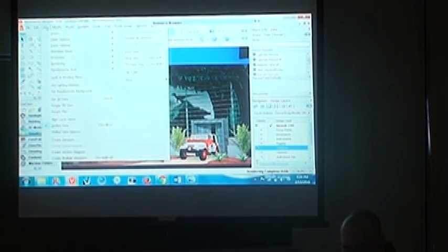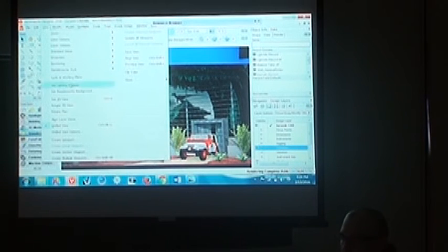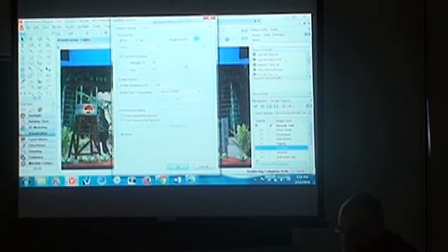Now I'm going to go up and adjust, you can see it says adjust environment lighting. So I'm going to go up to my set lighting options and adjust my environment lighting. My ambient light is really high right now, which is just washing out the effect of all those light objects that I put in. So let's just go ahead and turn it off. Woo.